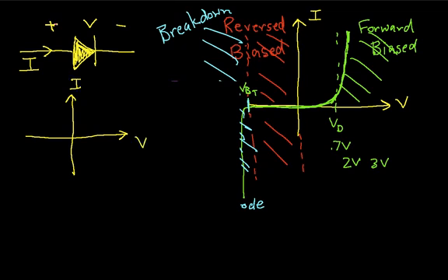we can take the line in the forward bias part and represent it by just a dashed line that's tangent to this forward biased curve at some point. So basically we have something that looks like this, where again this is the VD threshold, and then for all the other voltages below VD, we just have the current equal to 0.